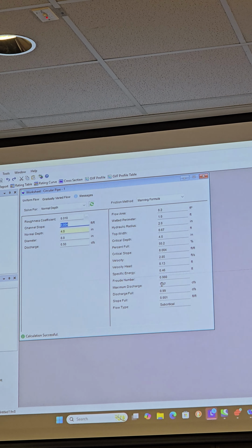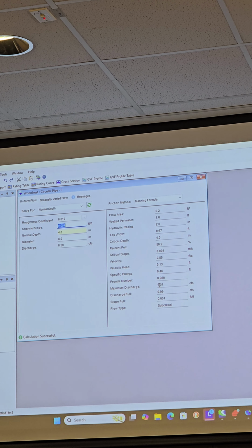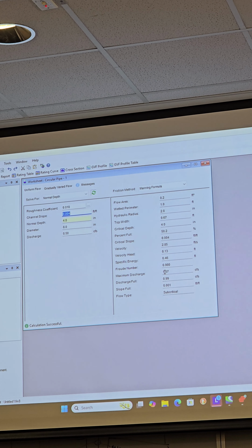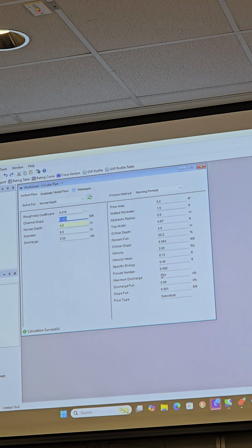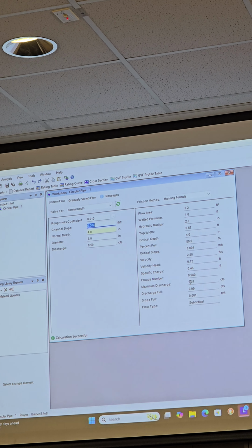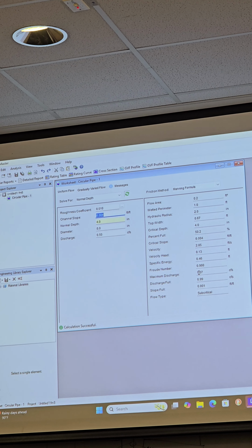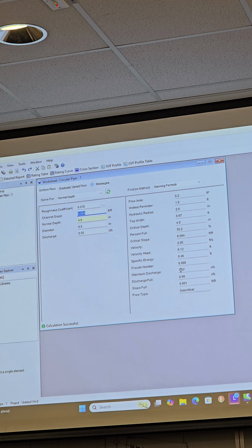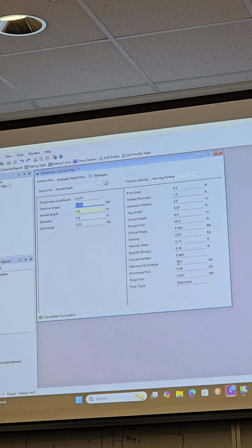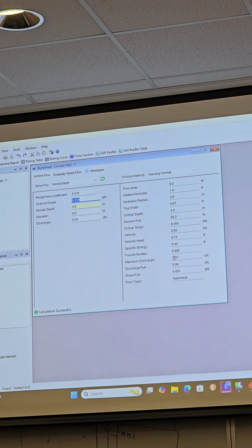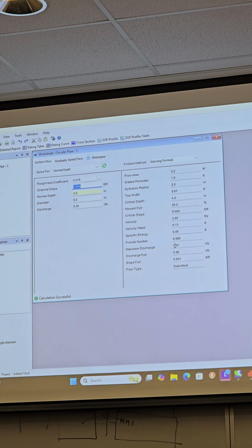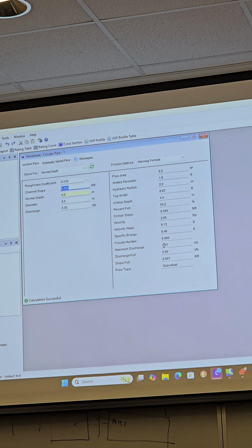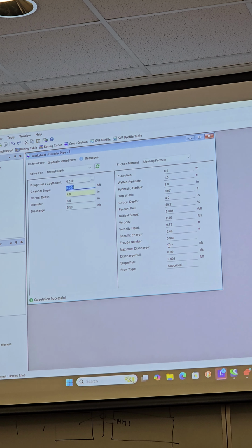Okay, so this is fairly straightforward, not complicated, pretty simple, so hopefully it makes sense. So again, your goal here is you're going to lay out your system, figure out your pipe sizes, figure out the inverts of the pipe, and then it's going to be part of a construction plan, so you show your manholes and your pipes. Okay? Yeah? So the material was PVC, right? The material is PVC. And that's pretty standard in Florida, PVC for sanitary pipe.